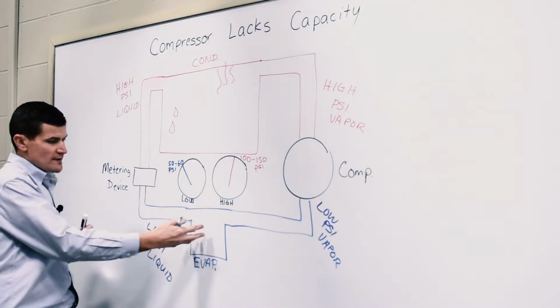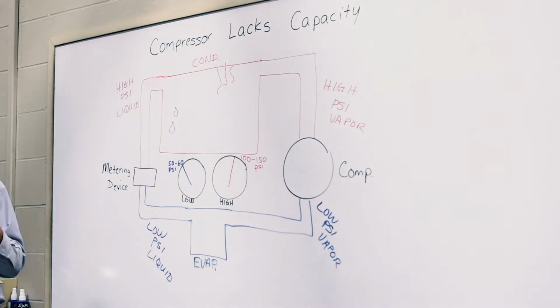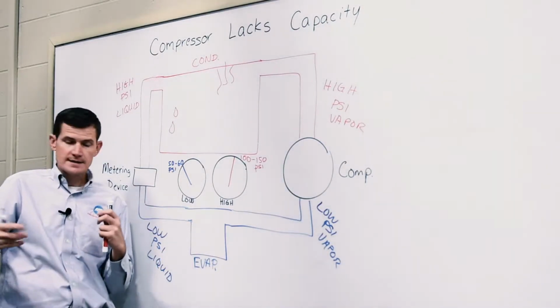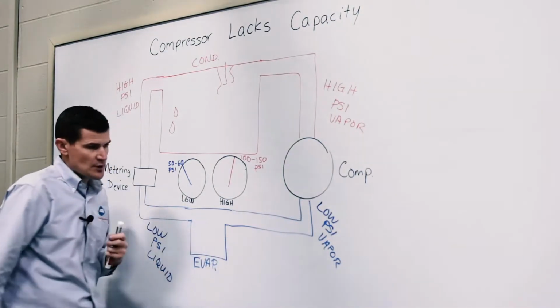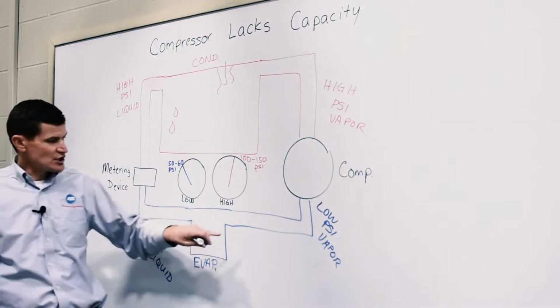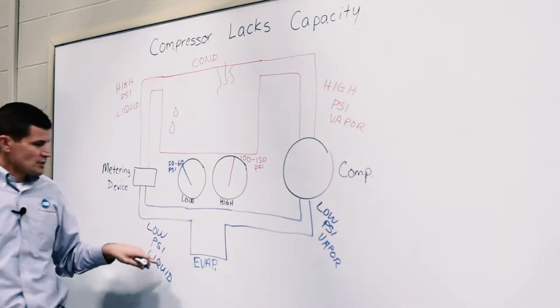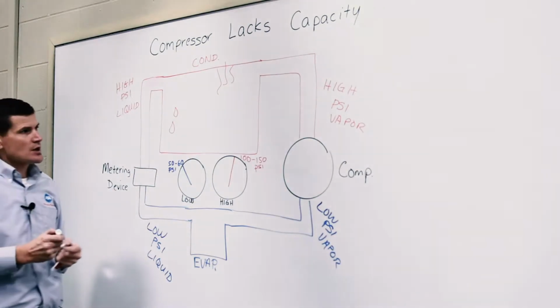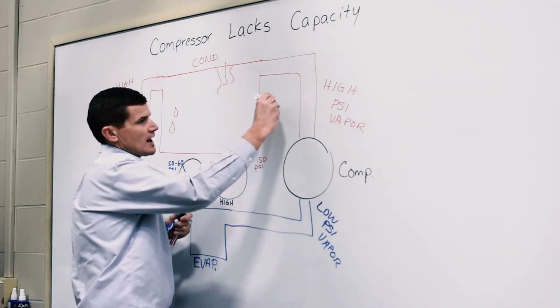It's going to go to the evaporator. We're going to have heat transfer, and it's actually going to cause the refrigerant to vaporize. And so coming out of this, it becomes a low pressure vapor. So again, we change state in the evaporator from low pressure liquid to low pressure vapor, and this is a complete loop cycle going in the counterclockwise direction.